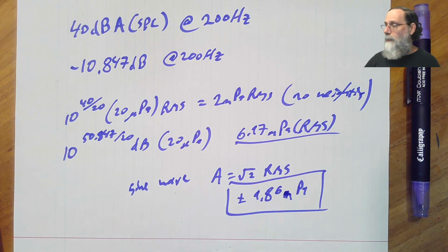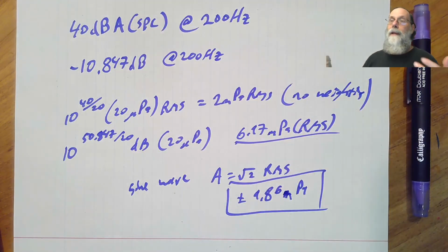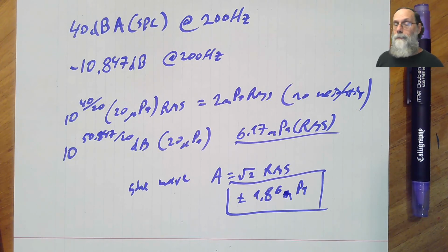And so you're going to need to know, how much pressure variation do I have in decibels? You can do all your calculations in decibels because essentially all your gains are multiplied. So if you specify the gains in decibels, because everything is now logarithmic, you just add things. But you can figure out how big is your signal, how much sensitivity does the microphone have, and so how much signal will I get out of the microphone. And that'll be coming up when we do the next video.